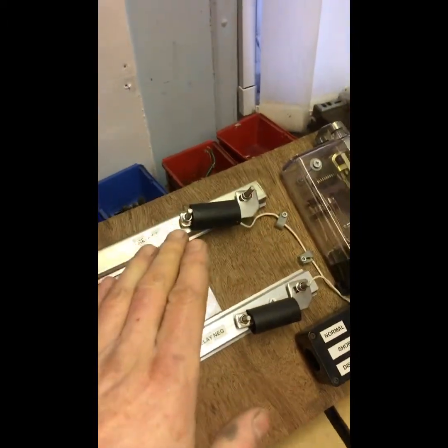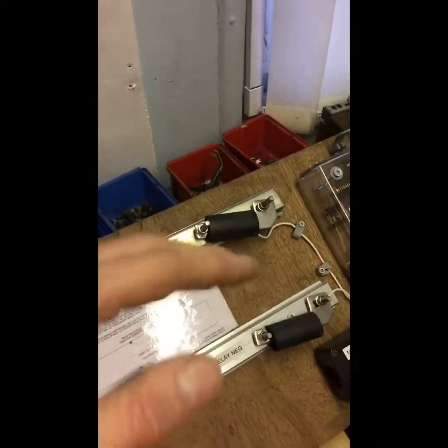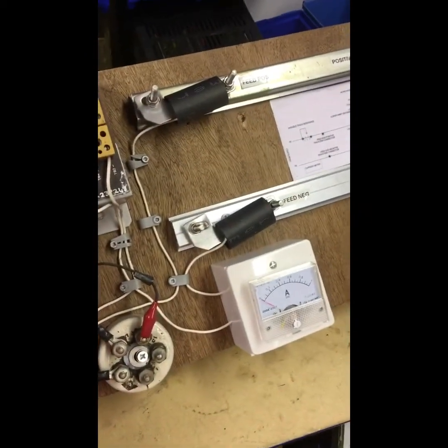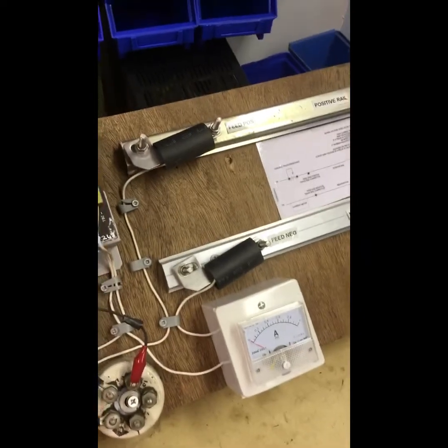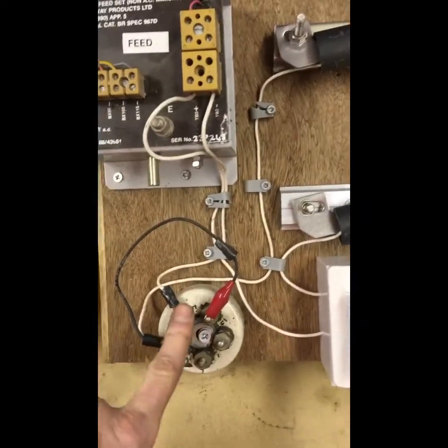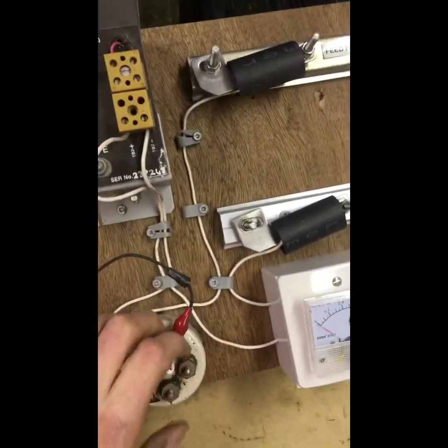So there is a formula for that. Over the 2 minutes you watch the voltage, see what it drops to, and within certain criteria whether the track passes or not. And this is just our demonstration little test set here. So you can appreciate that. That's what the balancing resistor allows you to do, to set up your shunting values, but also to protect against a short circuit when every train comes on the track circuit.